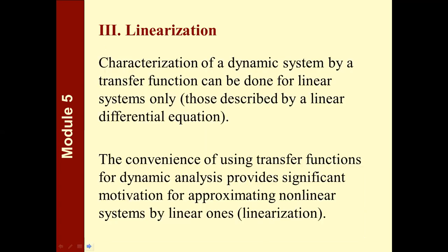Now, the process of linearization is the part wherein, as I mentioned a while ago, a term in your differential equation is not linear anymore. If the relationship between flow through the resistance would require that your h have an exponent other than 1, then you need to linearize that particular term.